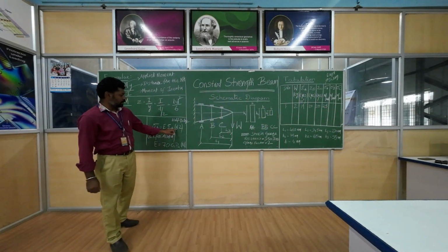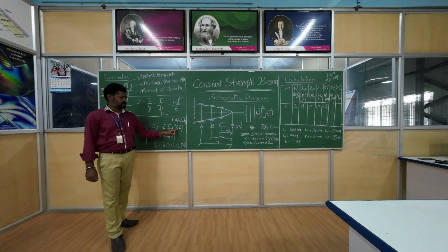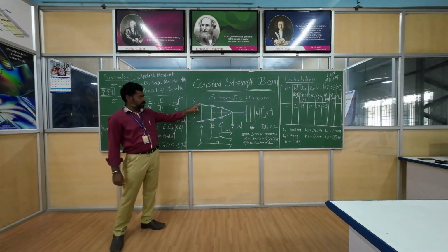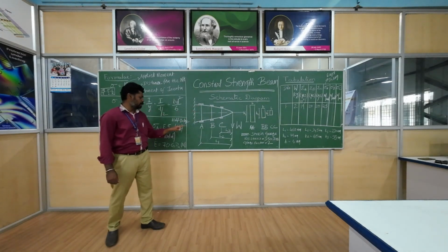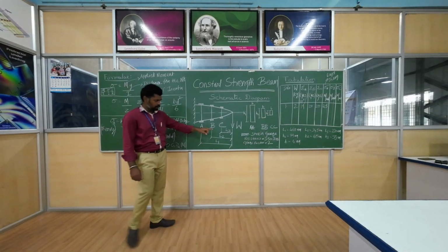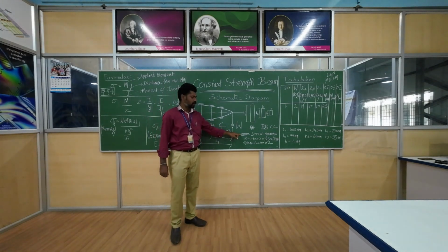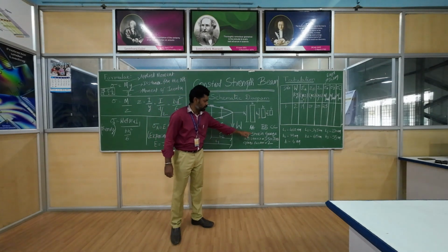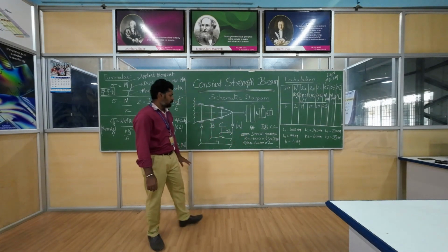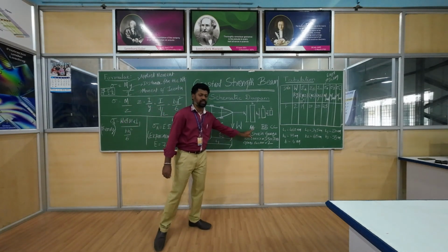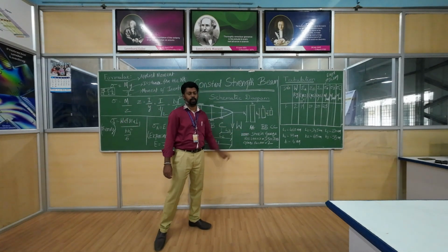Here, if you see, I am multiplying by 2. The reason is we use a half bridge circuit. That is why we need to multiply by 2. Here I have also given the strain gauge specification. It has a resistance of around 50 ohms and a gauge factor of 2. We will discuss the strain gauge later, in a separate session. As of now, just note down the details of the strain gauge which we are using in this experiment.